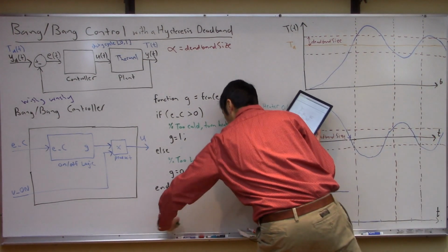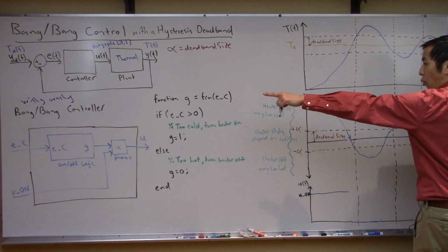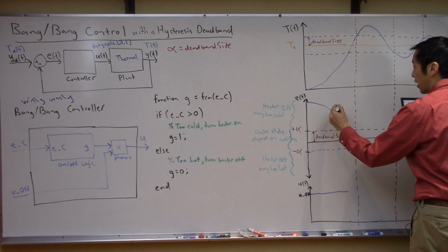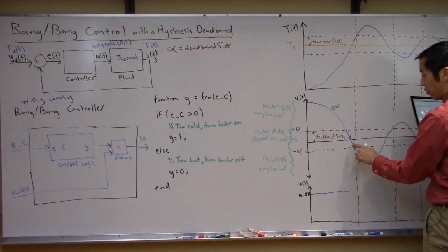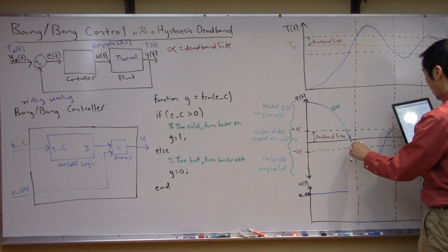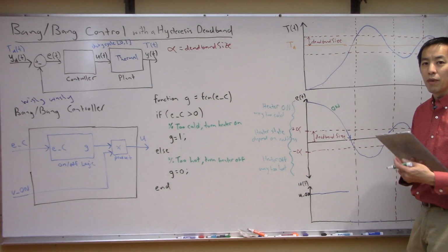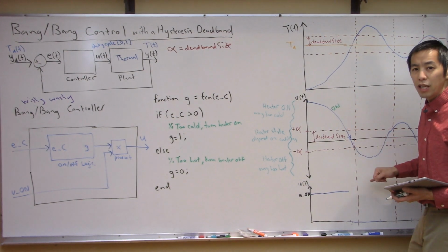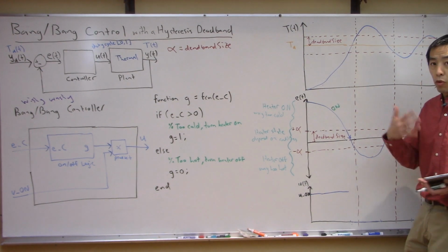What you want to think about doing right here is avoiding this wishy-washy problem. The heater's on out here, you're heating up, heating up. Now, inside this band, we are going to allow the system to stay on until we completely pass through this deadband. We're going to fully commit. It's go big or go home. You're not going to change the state of the control, to avoid this chattering.